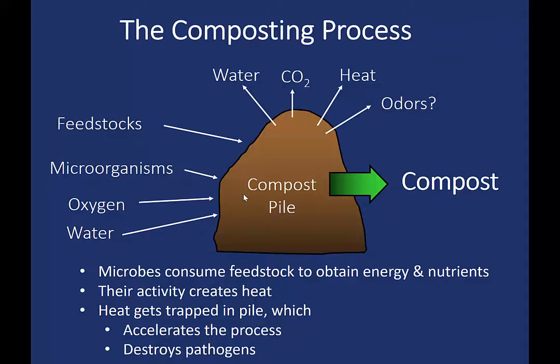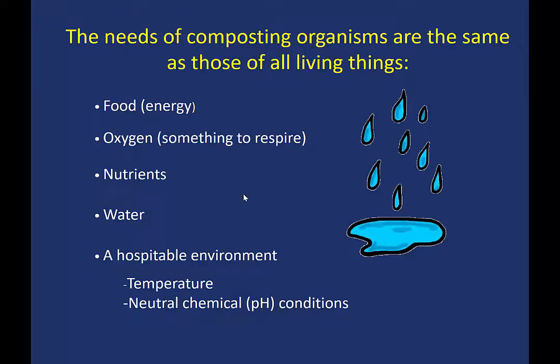So if I go to a compost pile and move the compost and I smell rotten eggs, that means I have murky anaerobic compost, right? I shouldn't smell anything because if it's an aerobic process, hydrogen sulfide shouldn't be produced and it shouldn't have any odor, okay? So if you go to a compost pile that smells, most likely it has gone anaerobic, and so it's no longer an aerobic process and you're getting that hydrogen sulfide smell. So hopefully we're not getting odors.